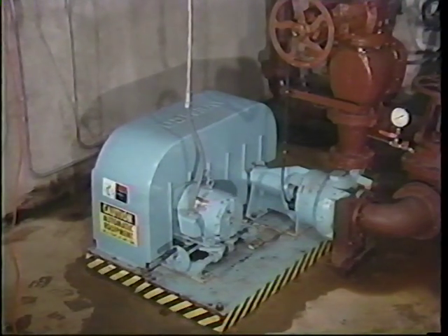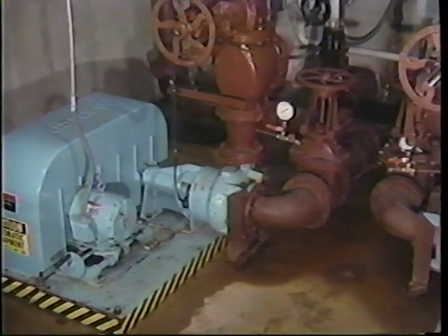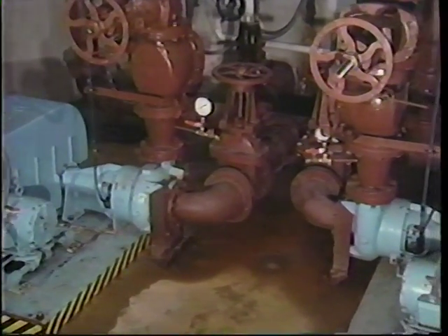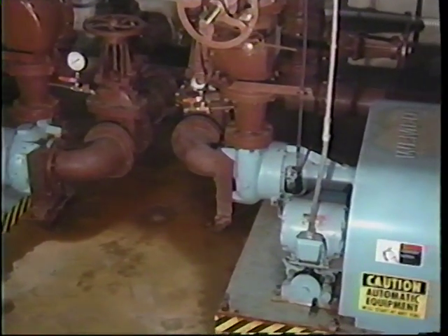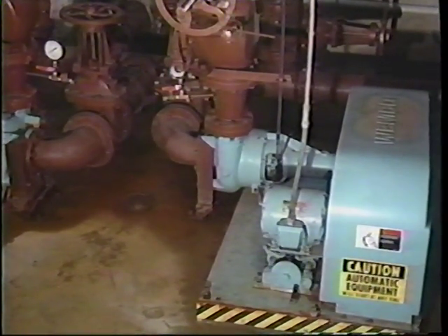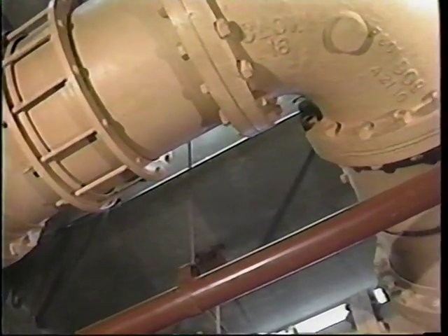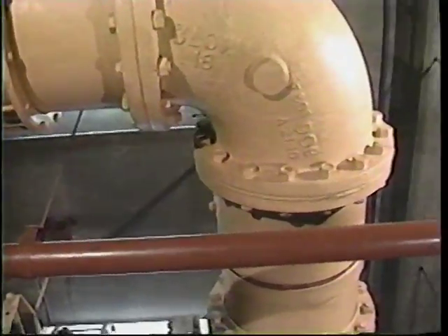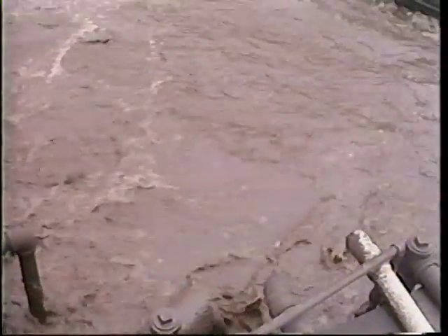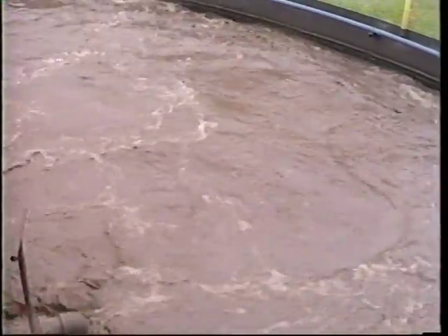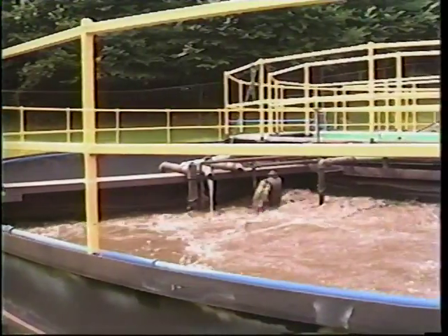Centrifugal pumps that are designed for solids handling may also be used for moving or removing solids. The centrifugal pumps are used commonly for removal of secondary sludges and for circulating the contents of primary anaerobic digesters. The majority of solids removed from activated sludge clarifiers will be put back into the activated sludge process, where the hungry microorganisms in the activated sludge will feast on the organic material in the wastewater.